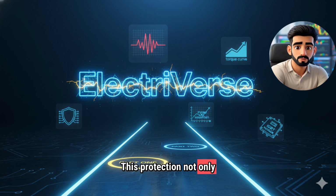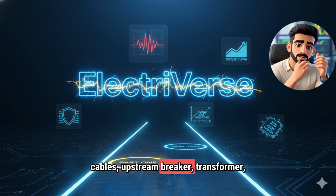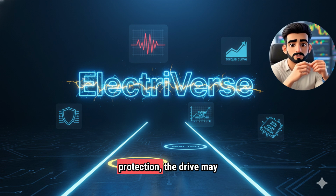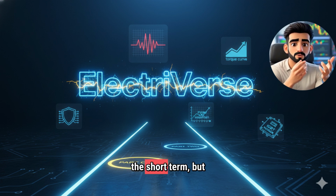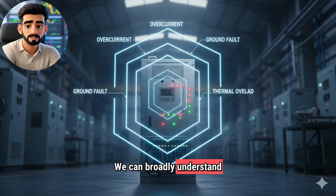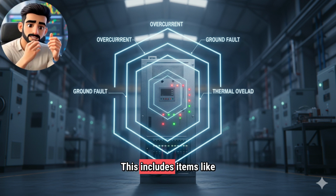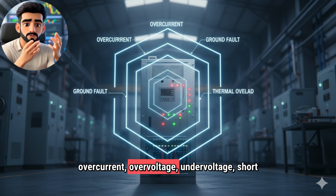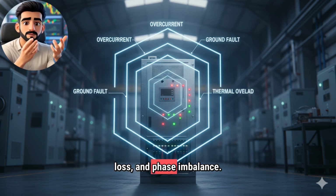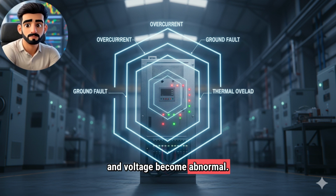This protection not only protects the drive but also safeguards the motor, cables, upstream breaker, transformer, and plant personnel. If you ignore the protection, the drive may appear to operate in the short term, but failure is almost guaranteed in the long term. We can broadly understand VSD protection in two levels. The first level is electrical protection. This includes items like overcurrent, overvoltage, undervoltage, short circuit, ground fault, phase loss, and phase imbalance. All these protections take immediate action when current and voltage become abnormal.